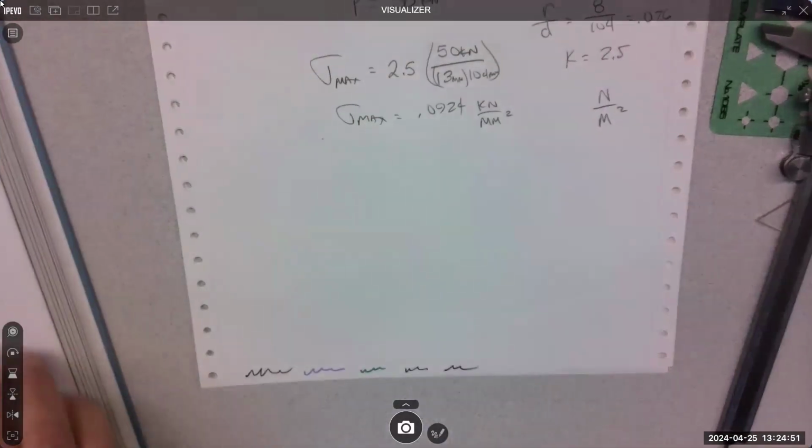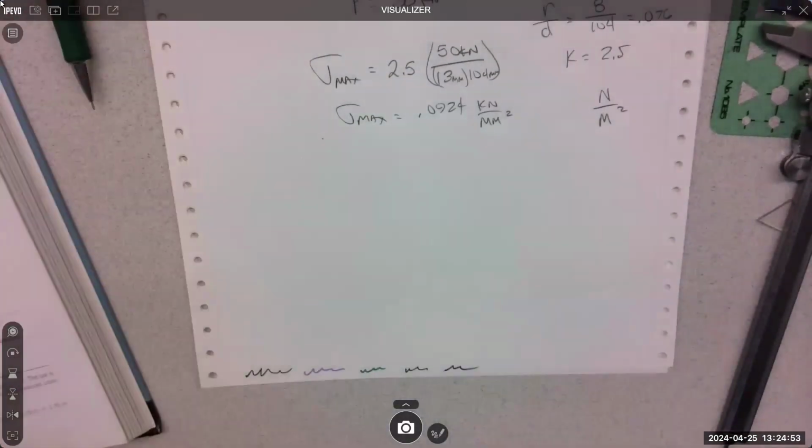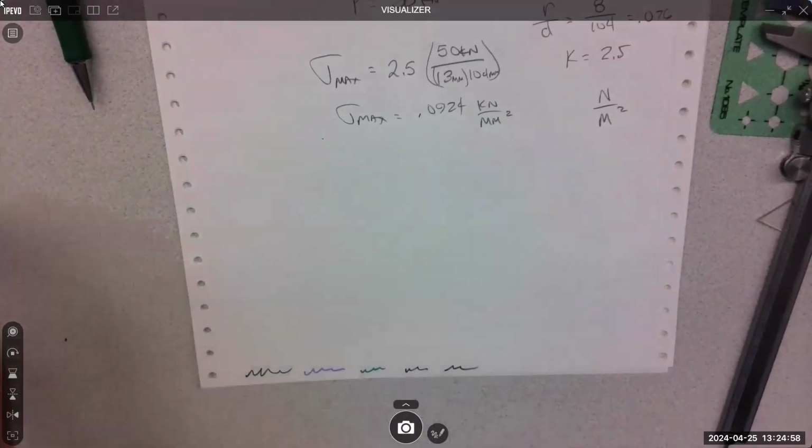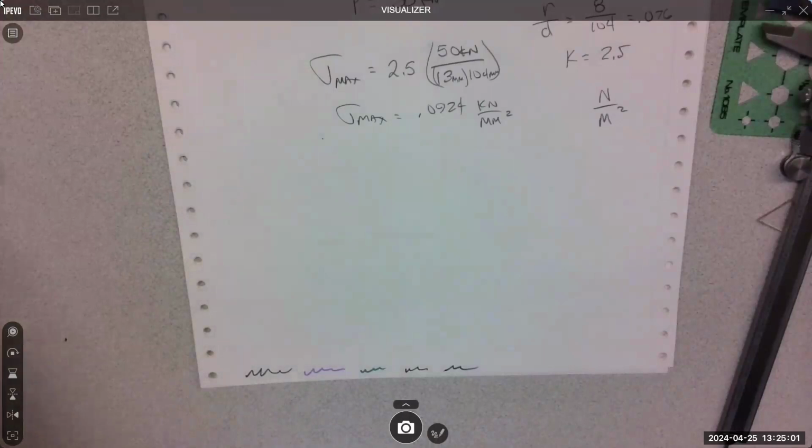So did they give us the material on this? Steel bar, but not, a steel, not bar? That kind of steel. Yeah, so if we just look up generic steel, anyone remember the yield for generic steel in the metric system? It's 250. Not to memorize, but if you think about it enough, these numbers for mild steel, which is a super common material, you'll start to just remember what they are. For the metric, mild steel, 250 for the yield.